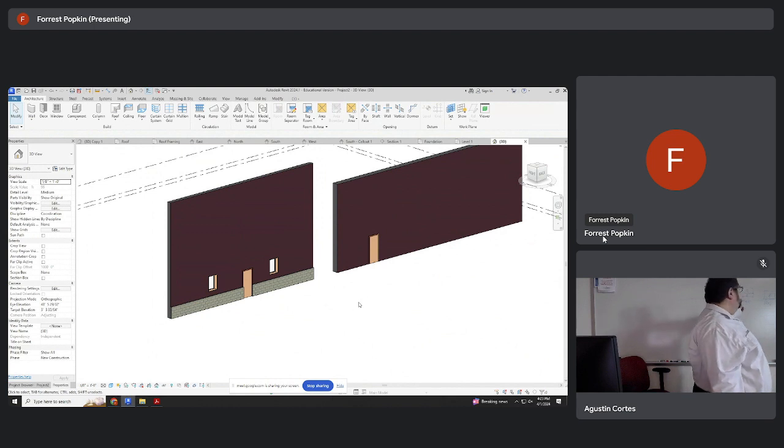You will also be changing your stacked wall, because all Revit's doing is putting them together and then putting some detailing on it, right? Does that make sense? So if you're going to have a stacked wall, be careful what you're doing with A's and B's if those are the two that you're putting together. It will make more sense as we do some practice.